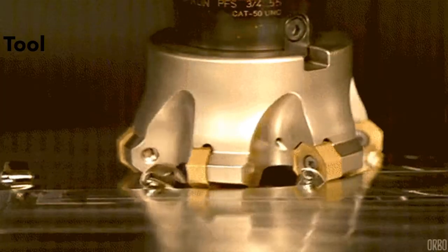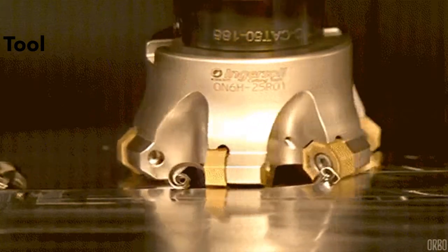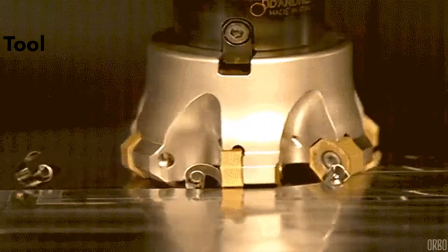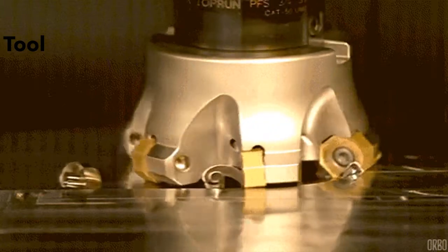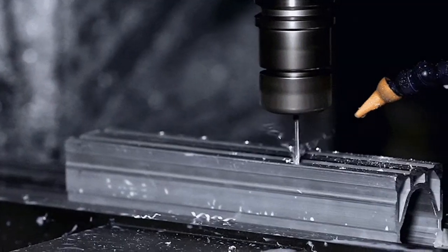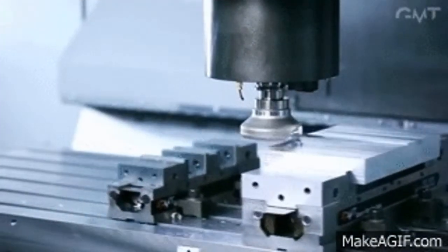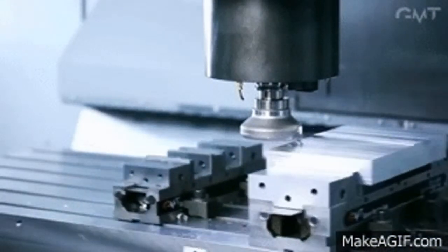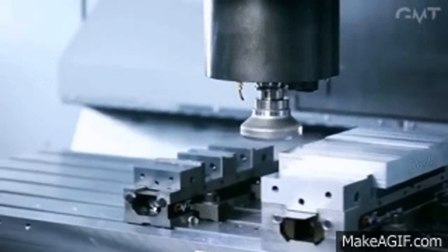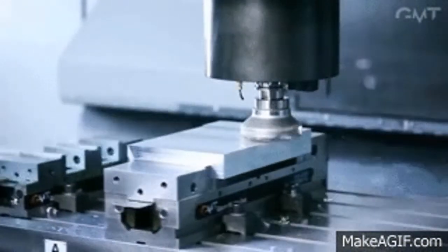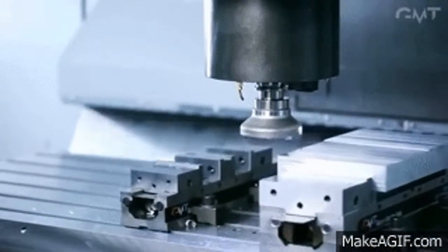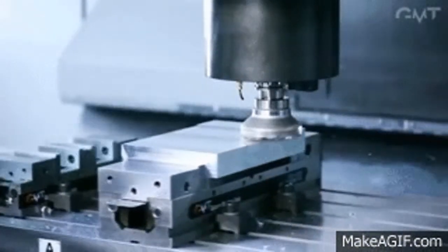Milling is a machining operation in which the work is fed past a rotating tool with multiple cutting edges. The axis of the tool rotation is perpendicular to the feed direction. The cutting tool is called the milling cutter, and the cutting edges are called the teeth. The machine is called the milling machine. Milling is an interrupted cutting operation, and the basic milling operation creates planar surfaces. However, other geometries are possible.